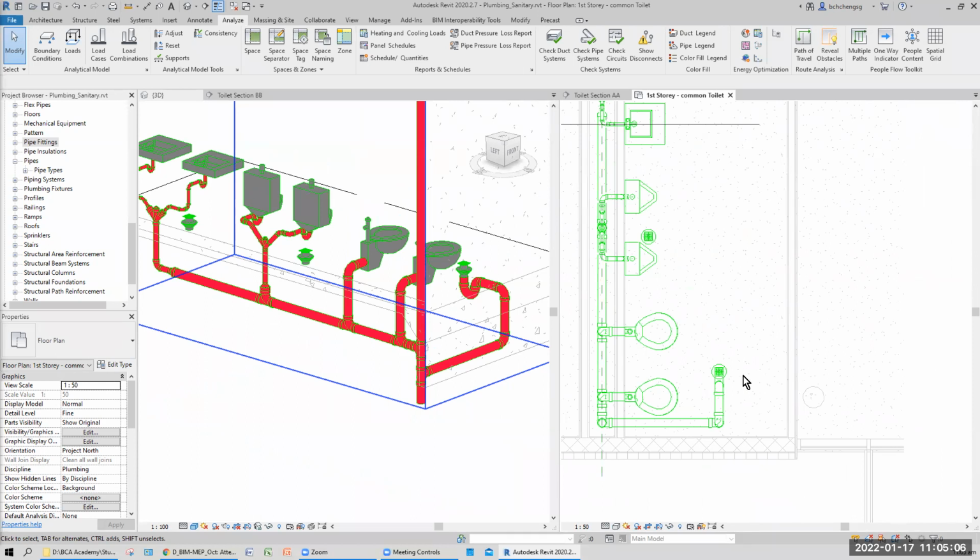Because you assume that this is the cubicle, and here normally is the walkway. That means your cubicle, you turn the L shape here, right? See now. So L shape here, unless some L shape here, there's a T. This guy can be blocked there. Because this side cannot be in the walkway. And it depends on the depth here. If my door here has a swing outside. All right, some toilets, their door is always swing outside. By right, it should swing inside. So it depends on how you want to design the WC, the cubicle itself.